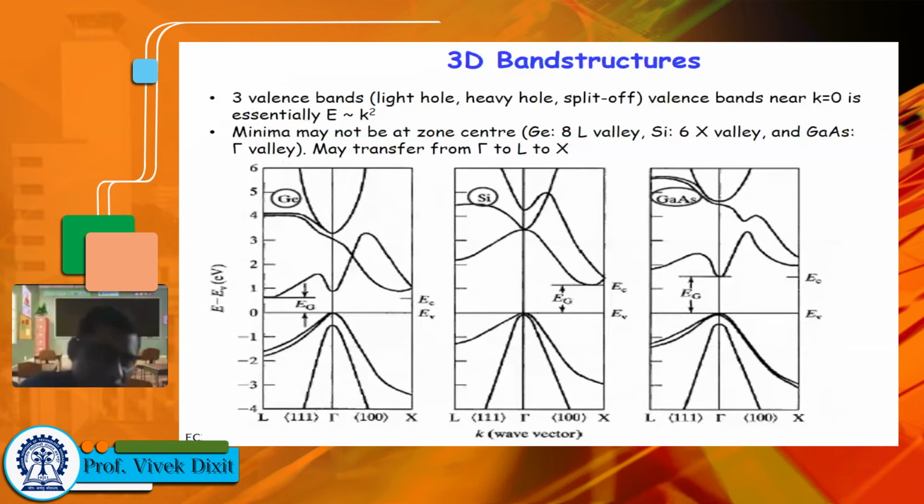So these are the band structures for germanium and silicon. So again, heavy hole, light hole. Okay, this is heavy hole. We see only 2 bands here. What does it mean? In case of silicon, we are seeing only 2 bands here, right? So this is heavy hole, and this will be split off basically. So that means heavy hole and light hole are basically coinciding. So they have exactly similar mass, right? So this will be split off.